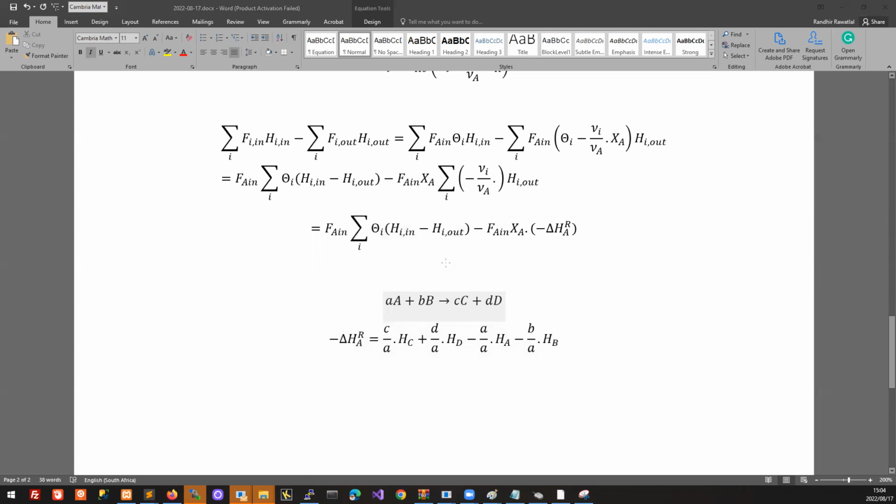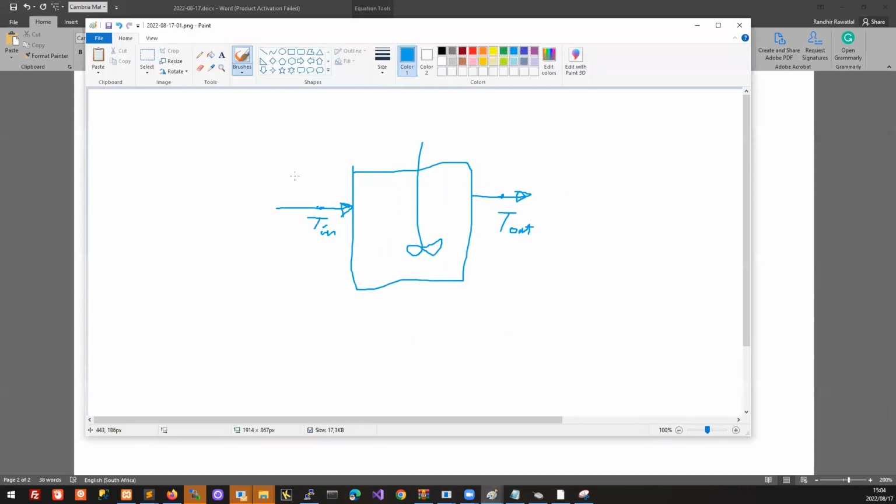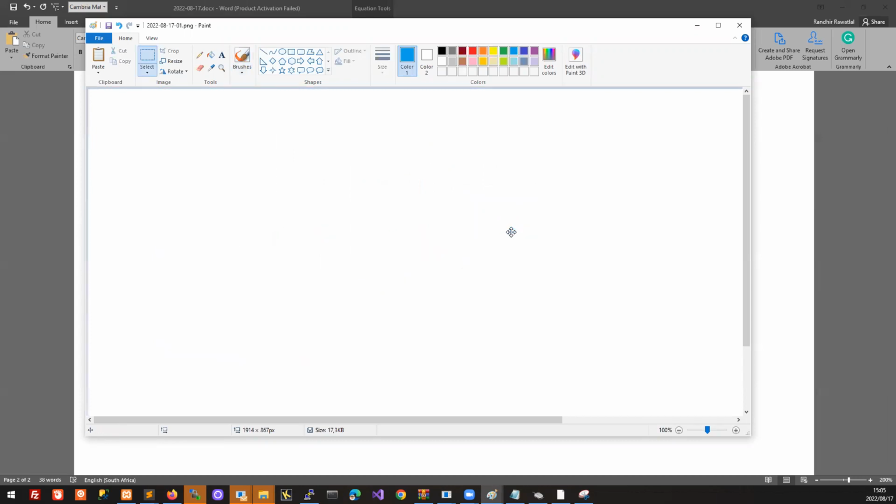And so if we go back to that picture we had before, oh no, I think I've saved over it now. But that one with the enthalpy, we said we start from a reference, then we jump to a new one, and so on. So let's do it here. We've got enthalpy in temperature, and so we can go from here to here. Then in the liquid, it's here to here, and then in the gas, it's something else. And so we can evaluate the change in enthalpy by looking at the change in temperature.